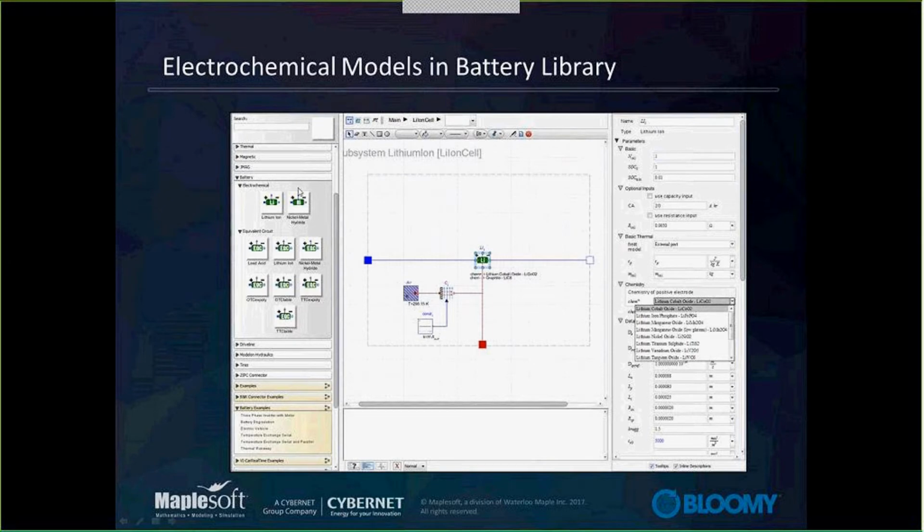We can easily do that by looking at our MapleSim environment again, where we can drag our model of our battery into the environment, connect it to any of the circuit components that are outside of the battery cell that we're interested in, and start bringing in some of our thermal library characteristics like we see here, where we can have our air cooling to some kind of external air supply, or even if we have connections to other areas like liquid cooling.